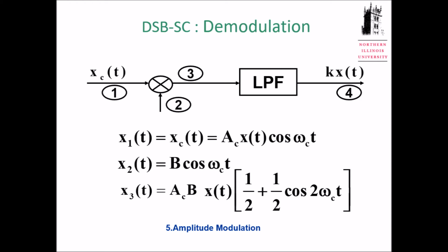So look at this signal, right? This signal is V cosine omega c t. We have a carrier, a pure carrier, mixed with the input. Then my signal will go through a low pass filter. After that, we get the message. So let's take a look at what's going on at every step. Okay, the input signal, right? A_c, the carrier amplitude, message, carrier. Point B, my signal we just mentioned, right? Pure carrier with a little different amplitude.